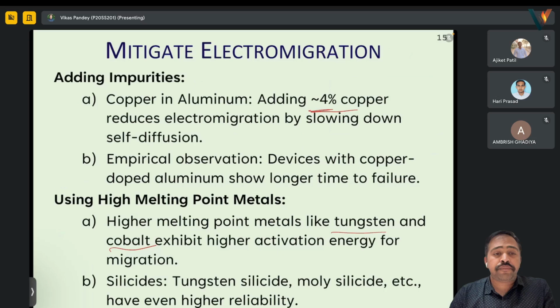So copper actually has a defect. It creates very low silicon and causes significant damage to device performance. And then at low temperature, we are talking about 400 degrees Celsius, because some processes or even thermal operation can be at that temperature, and it can diffuse through the dioxide, not just silicon.